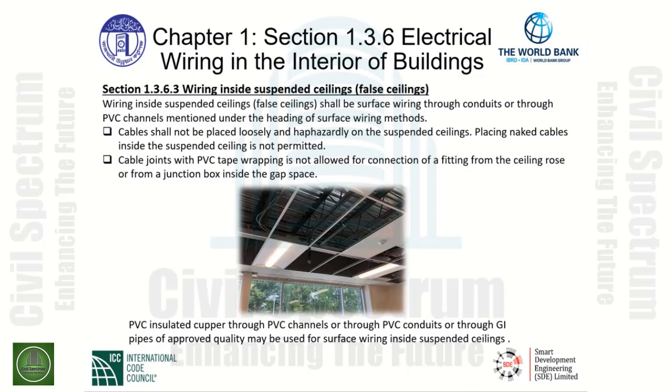Wiring inside suspended ceilings or false ceilings. Section 1.3.6.3. When we have wiring inside these spaces that we call false ceilings, it shall be surface wiring through conduits or through PVC channels mentioned under the heading of surface wiring methods. Therefore, we must go back to the previous section regarding surface wiring methods for this particular area within our